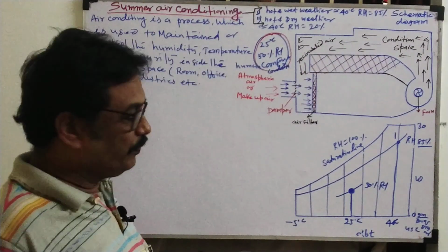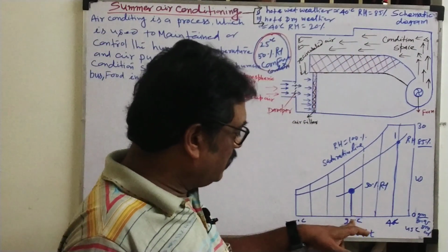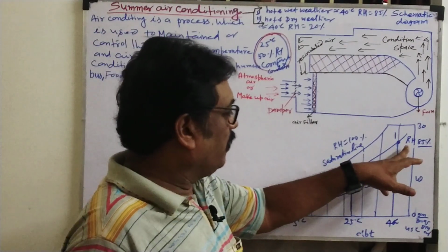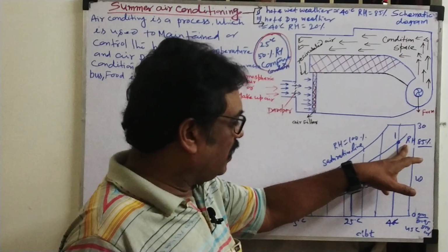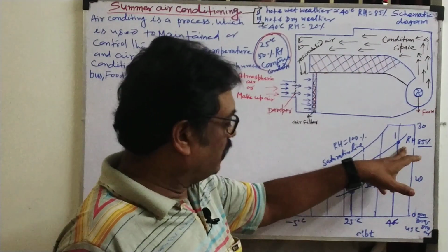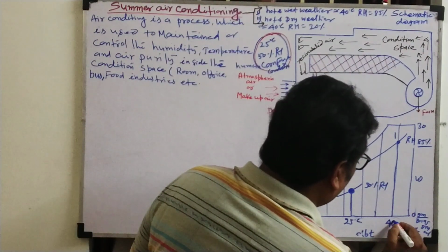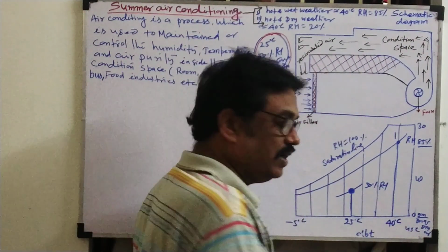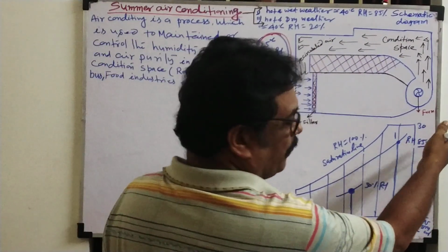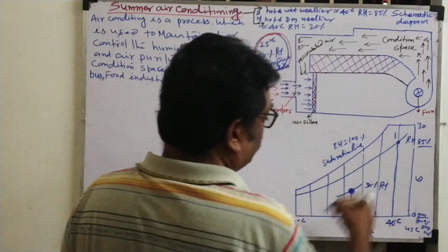So now you see, in June, July or summer, our comfort condition will be this. This is the temperature the human body likes. And the first condition at that time was here. We are here. So that means the temperature will be approximately 40 degrees Celsius. You can say 38, 42, 43, anything. Relative humidity also approximately 45 to 90%. First condition here. How to reach here?